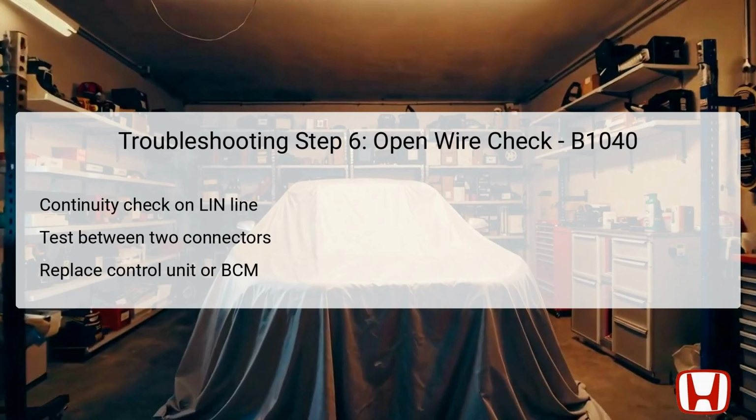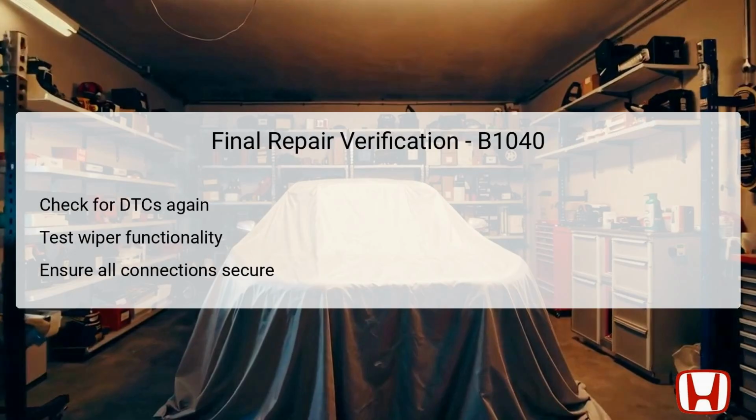However, if continuity fails, this indicates an open or poor connection in the wiring itself, necessitating further diagnostics on the wiring harness. Once repairs have been conducted, it is vital to verify that the issues have been resolved. Begin this verification by checking for DTCs through the Honda Diagnostic System, HDS, once more. This step checks if DTC B1040 persists or if the system is now error-free.